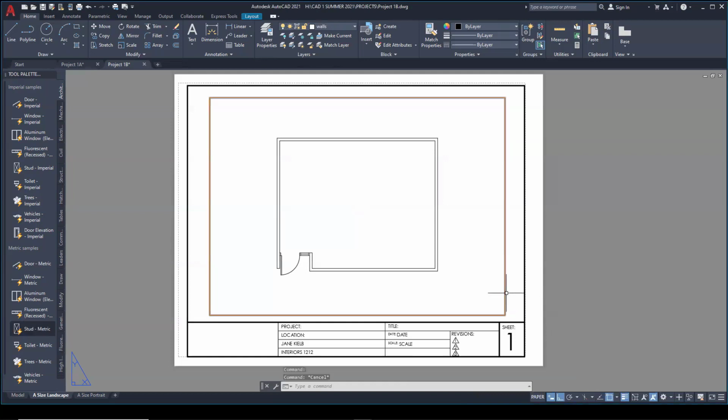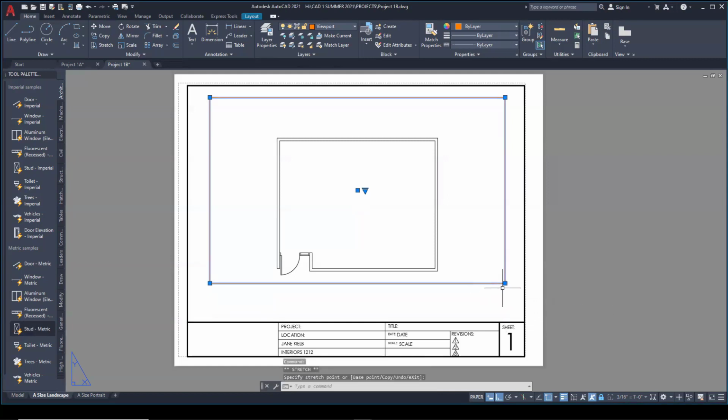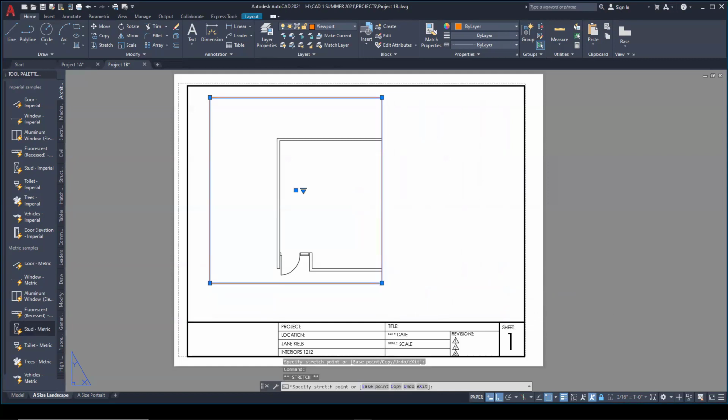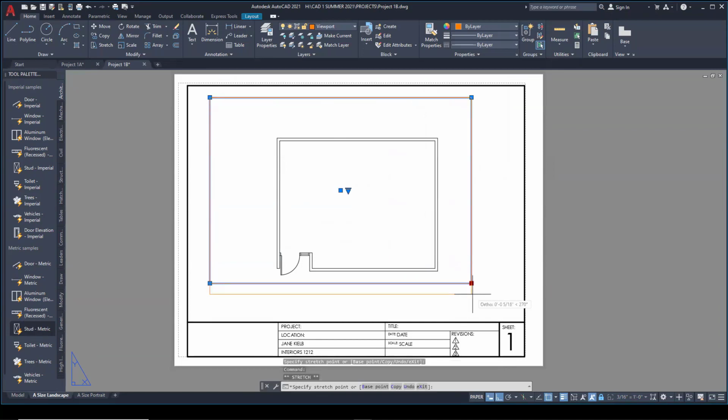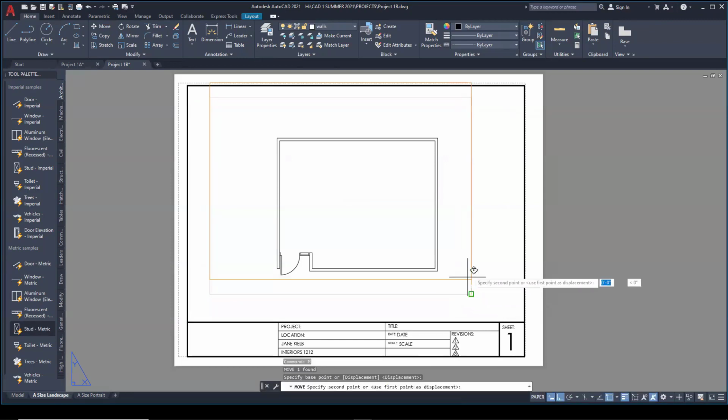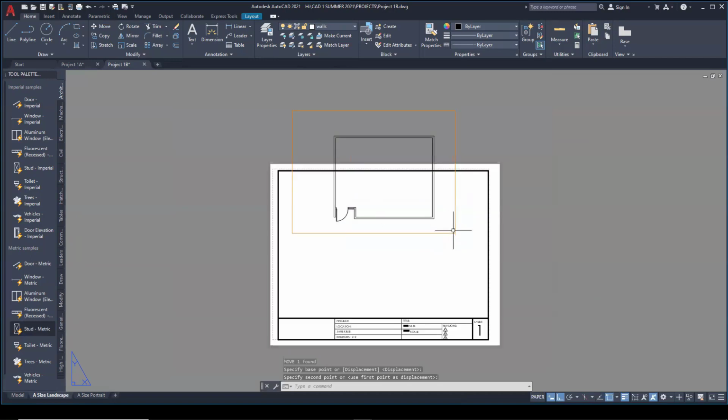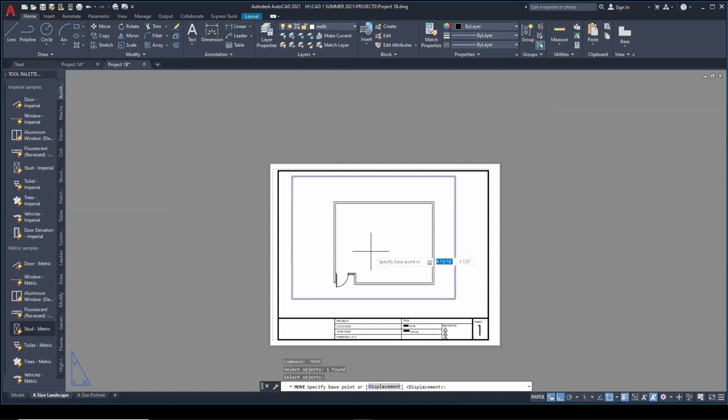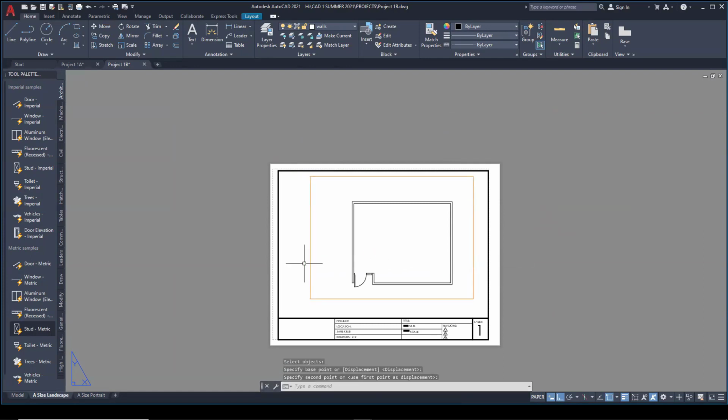By the way, I can do this. I can change the size of my viewport. The viewport's locked. I think I can. Yep, I can change the size of my viewport. And you notice that part of the image is cut off because my viewport is cutting part of it off. I'm changing the size of the window that I cut out. And I can change the location of the viewport by using the move tool. So I can move that viewport wherever I want on my sheet of paper. And then you'll just enter your dimensions, clean up your